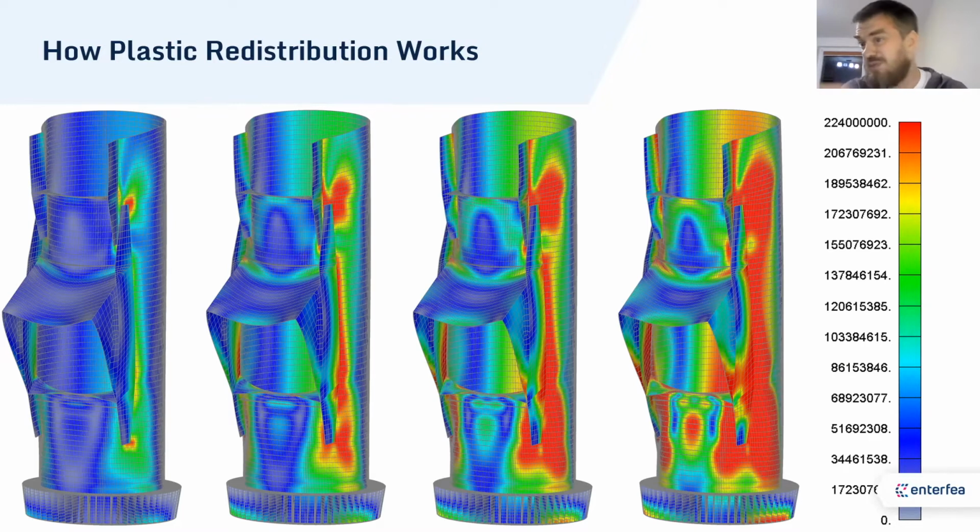So when did the failure happen? And the funky thing is that you don't know based on this. And that's where people usually tend to say, oh, linear FEA is stupid, let's do nonlinear FEA. They do whatever, they get a nice picture and say, see, it works. But realistically speaking, there has to be some sort of limit that would mean, okay, this is okay or not okay, right?